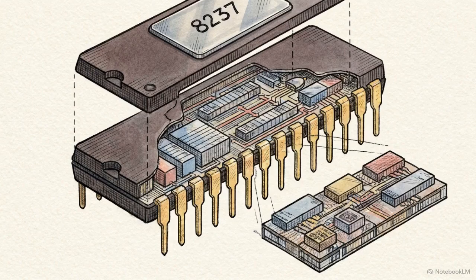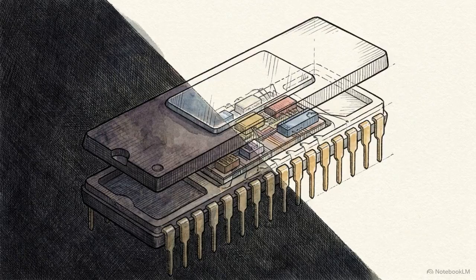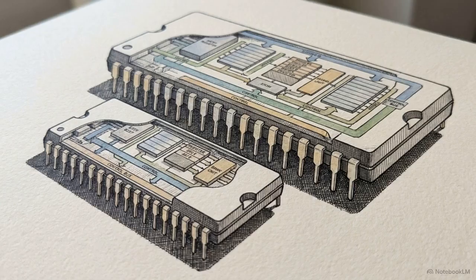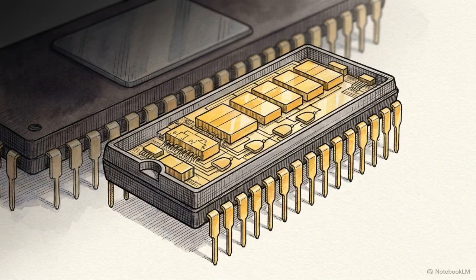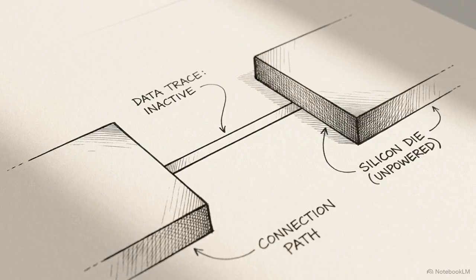In many early microprocessor designs, this direct pathway is governed by a dedicated chip known as the Intel 8237 DMA controller. The 8237 operates in a split-state reality. Most of the time, it acts as a standard slave peripheral, taking instructions from the CPU. But when a transfer triggers, it steps into the role of the master processor, taking physical control of the system buses.